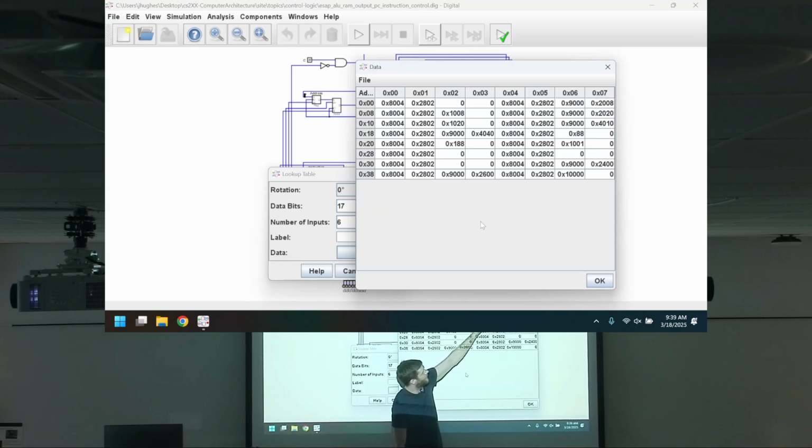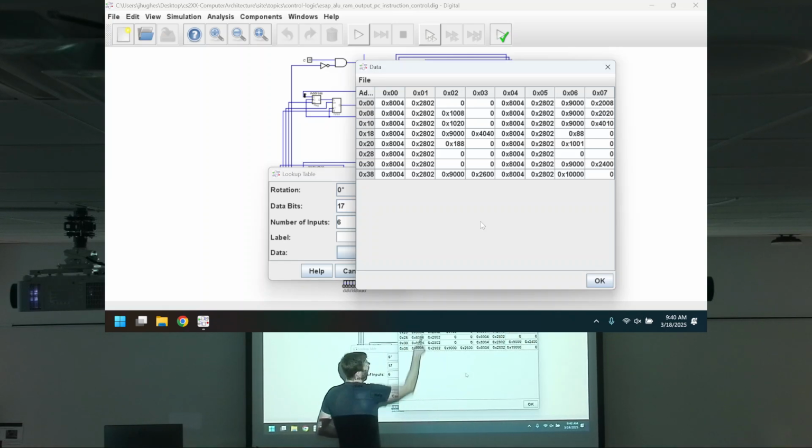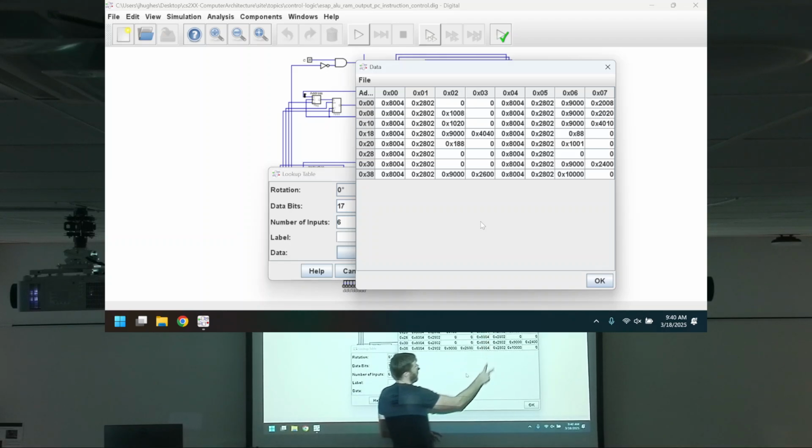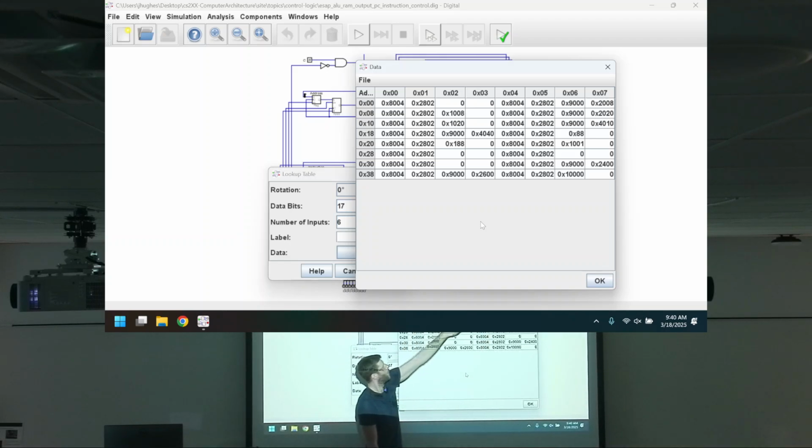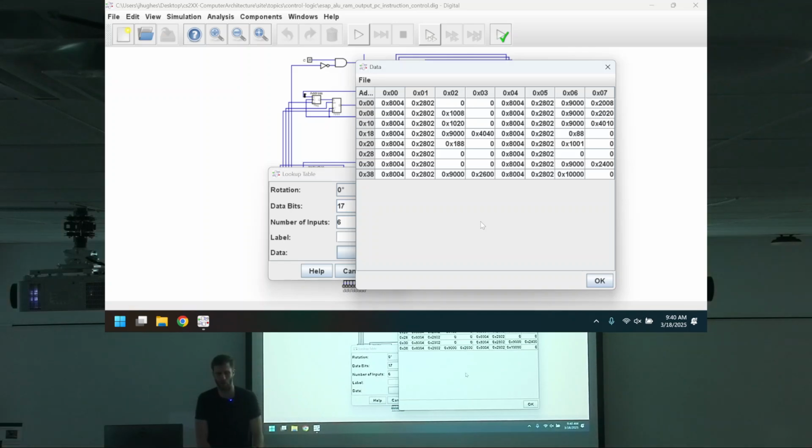This is the hex pattern for the 4 microcode steps of load A from RAM. You'll notice that these are always going to be the same, because these 2 columns are the fetch. So we have 4, 4, 4, 4, and so on. So that should be 64 total things. Right? 16 times 4, or 4 times 16. Cool. So there we go.